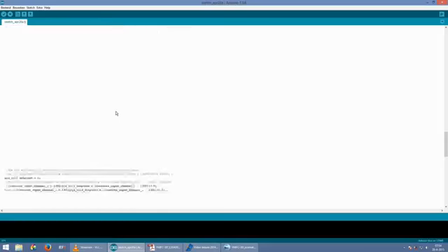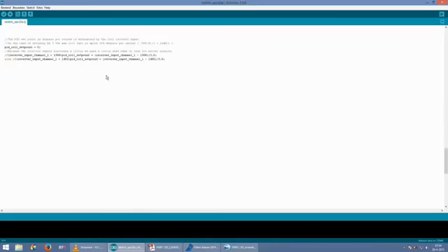To transfer receiver inputs to degrees per second is a little bit different. Not everybody flies with the same roll and pitch rate. First we set the roll setpoint to 0. The receiver inputs fluctuate a little, so we need a little deadband. This prevents the fluctuations of the receiver signals from ordering the PID controller to do something.